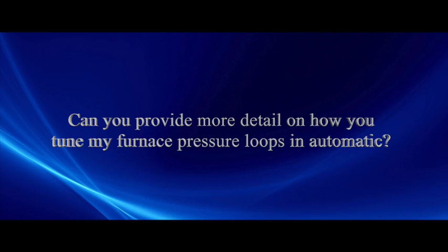When we did these tests, we would very closely monitor it, and I would increase the gain and make a little set point change to get it moving. Otherwise you're waiting for something to happen, and you don't want to keep increasing the gain. So you take the reset out of the picture, you make a very modest increase in gain, maybe 10%, 20%.